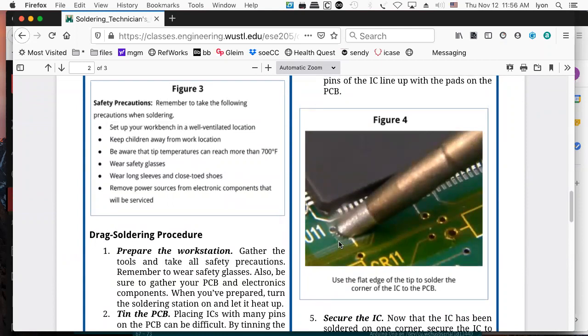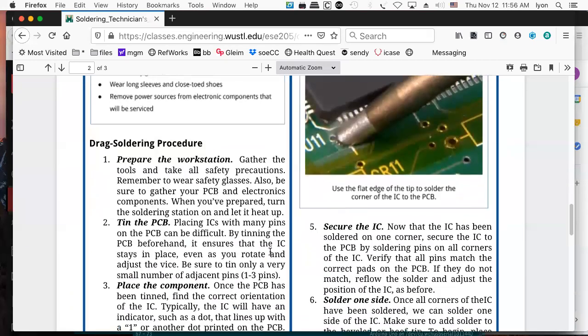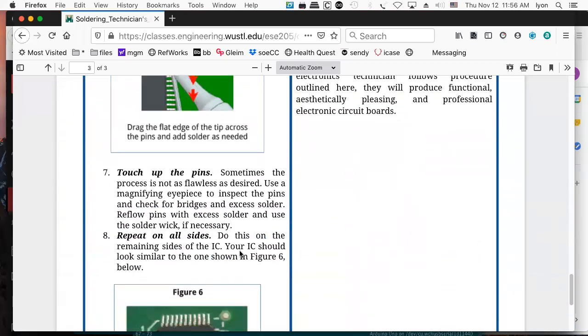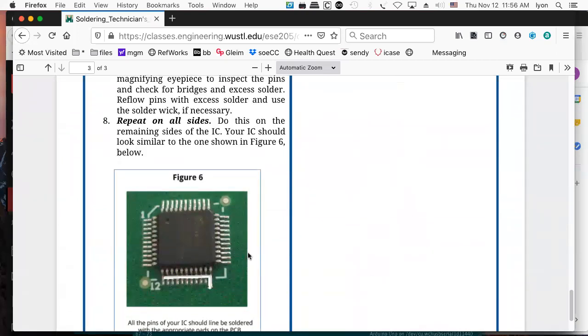Yeah, definitely not. It's not like the little one. If you try and do these little guys without bridging the tips, I know a guy who is excellent at it in Stratford who will do it. You can do that sort of thing without going through a reflow. And here he's dragging the tip and feeding the solder at the same time. It takes a bit of practice.